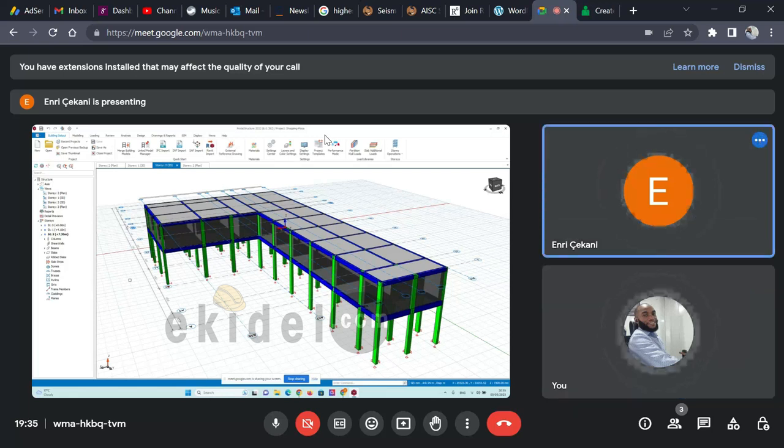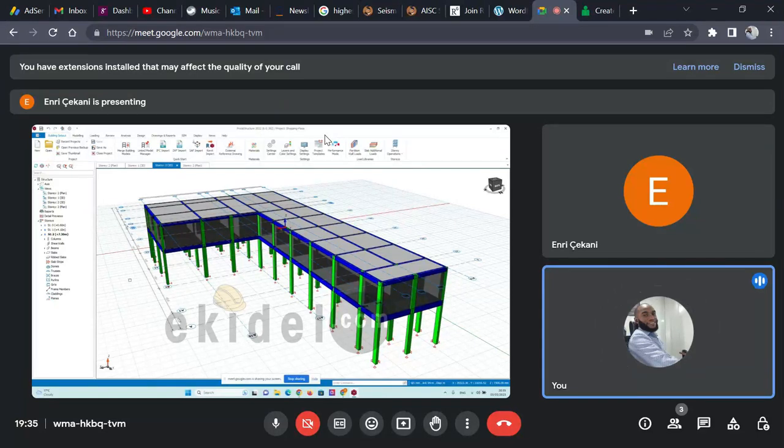I'll also show you that later. But first of all, for the sliding shear, EC8 introduced what they call bi-diagonal reinforcement, which controls uplift. Bi-diagonal reinforcement is like an X along the beam: you have cross diagonal reinforcement along the beam.